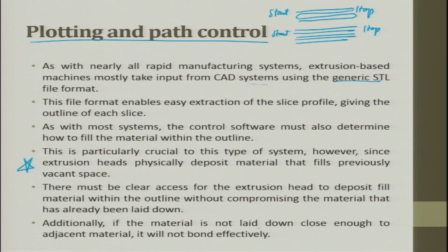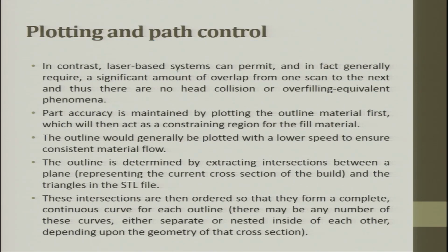Additionally, if the material is not laid down close enough to the adjacent material, it will not bond effectively. In contrast, laser based systems can permit and in fact generally require a significant amount of overlap from one scan to the next, and thus there are no head collision or overfilling equivalent phenomena. One spot, the other spot, this is a laser spot.